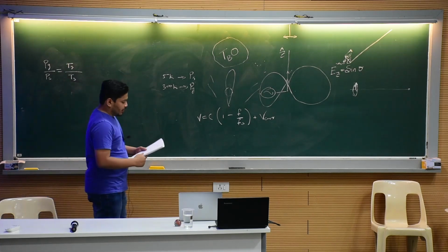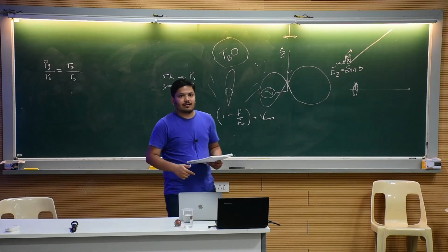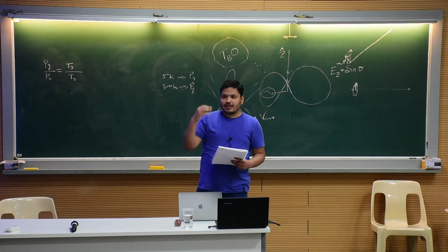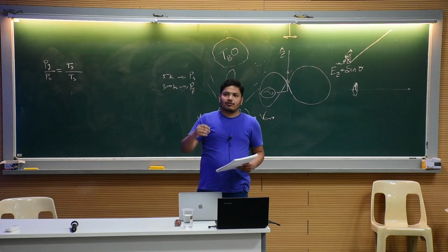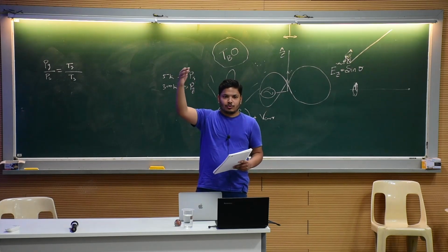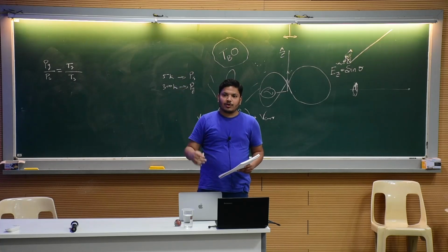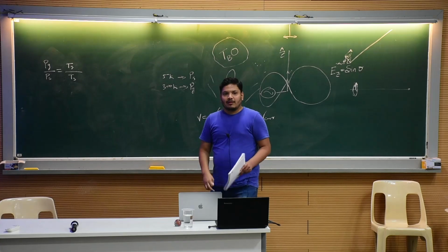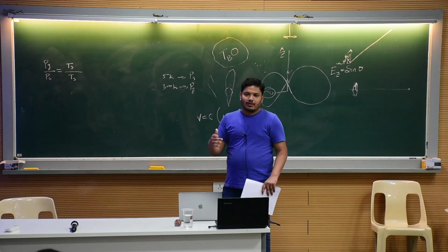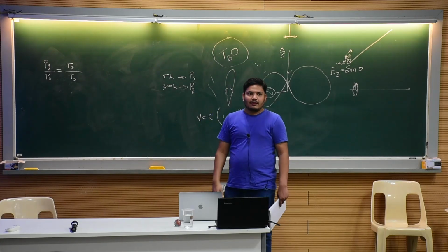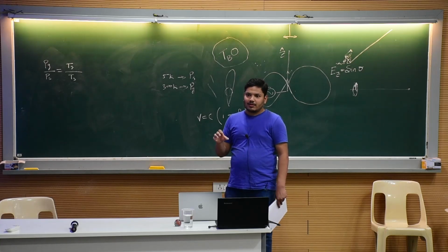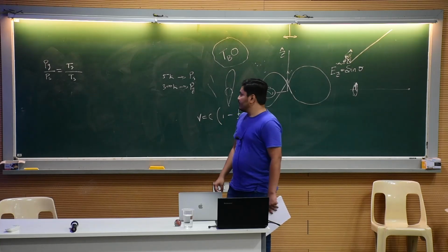Yeah, but when you point the antenna to a source, it will of course have the contribution from the source, but it will also have contribution from the system itself. So we are assuming a very simple model where your system is also contributing to this temperature. So we'll first have to figure out how much your system contributes to the temperature.